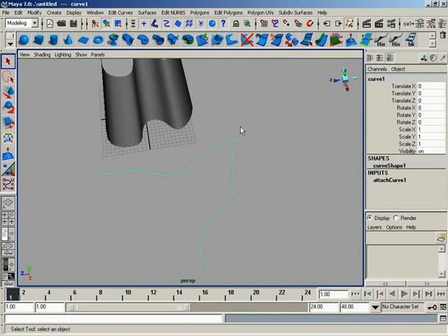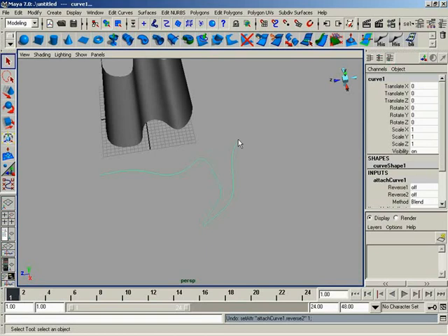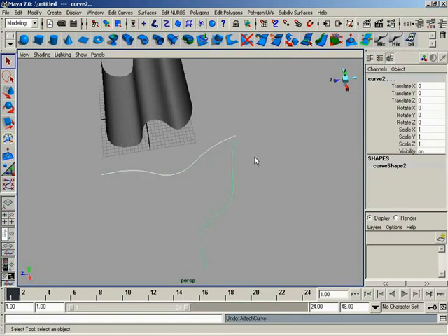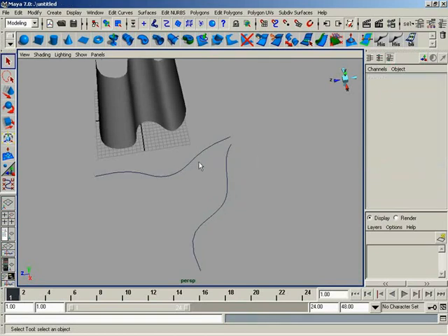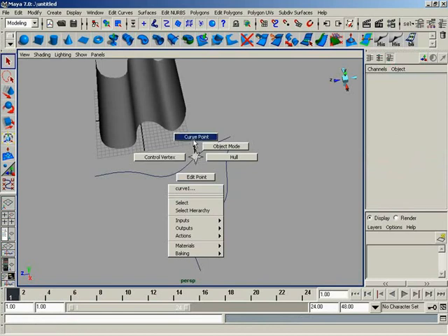The only problem is that sometimes Maya will guess wrong, and you're going to discover that as you work more and more with NURBS surfaces. If you're ever trying to avoid a situation where Maya will have to do any guesswork whatsoever, you can specify a specific point along a NURBS curve to do an attachment.